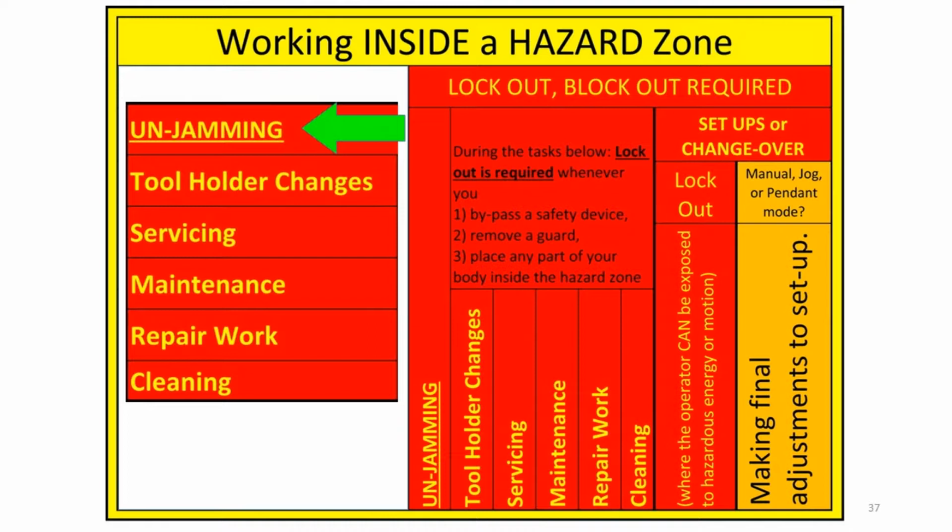Be aware though that if you do reach into an energized machine with a tool, use only tools that can't pull you into the machine if the tool itself gets caught. Avoid tools with hook-shaped handles or straps that would go around your wrist.